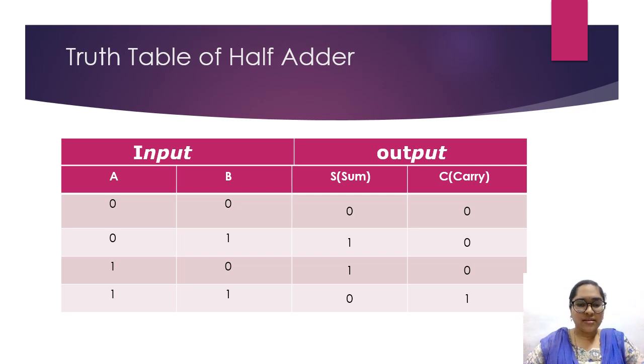So basically we take this 0 0, 0 1, 1 0 and 1 1 as inputs, and here we have the output sum. For sum, output is 1 only when the inputs are different. So this basically represents the XOR gate. In XOR gate, the output is always 1 only when the inputs are different. So now let's look at the carry. So here carry output is 1 only when both the inputs are 1. So this is the property of AND operation. So this sum and carry basically perform the logic gates AND or XOR operations that are